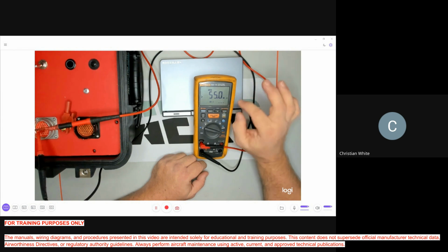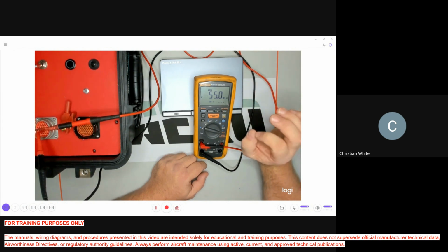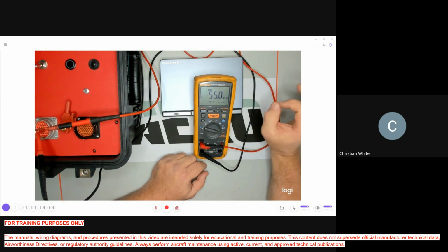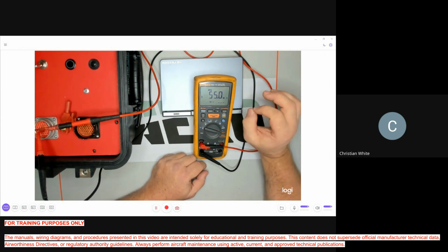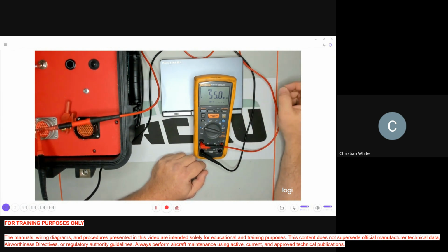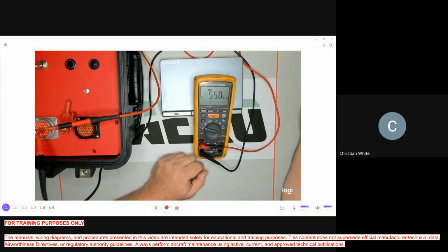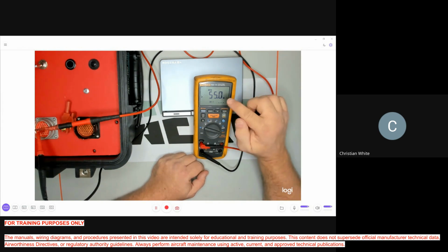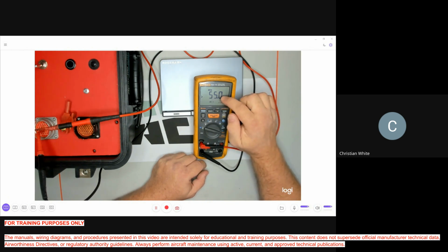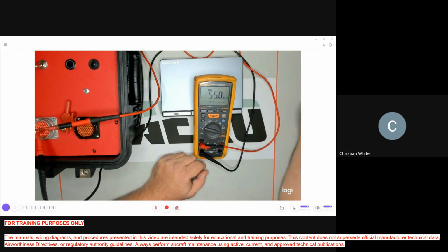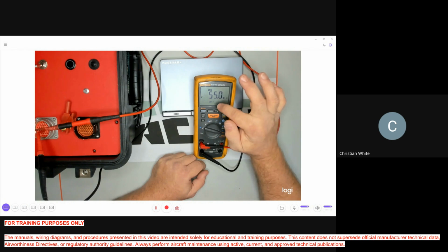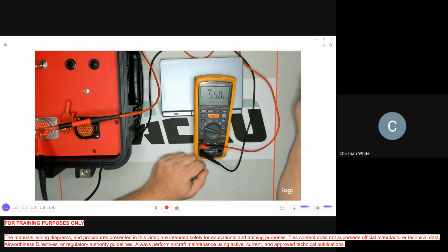So every time you do a test, when you're going to a new connector, you looked at the wire diagram, you said, okay, I know it's pin 2. So you're always going to do your first test at 50 volts. 50 volts, if you accidentally shoot through a box, is not going to hurt the box. However, if you see something at 50 volts, if it shows anything up, you better make sure that you have everything disconnected you should have. Otherwise, you're going to fry something. So 50 volts is a fairly safe way to go to start.